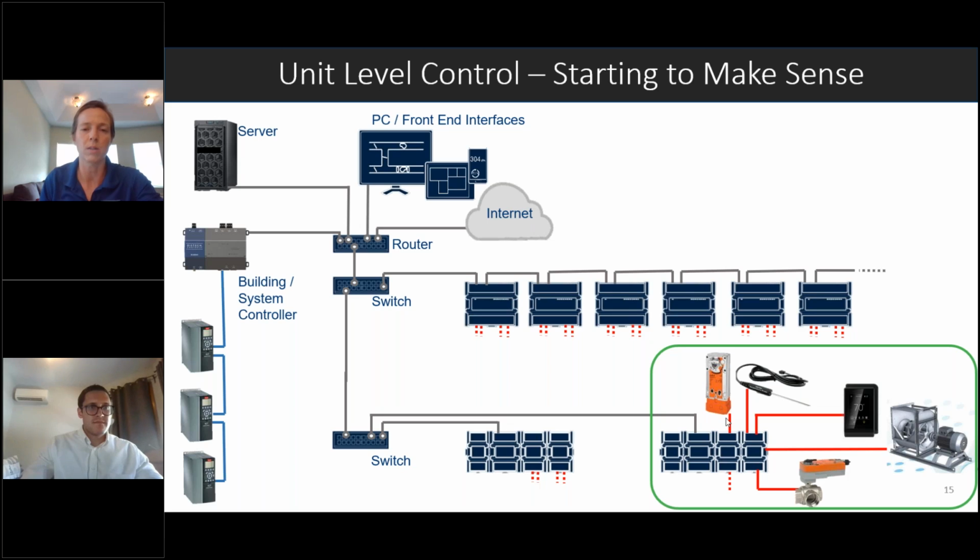But as Grant alluded to earlier, you have to read the documentation carefully, because sometimes there are some field installed sensors and wiring that you need to do. So factory package controls can mean everything from fully packaged, where you just need to bring one cable so it can be tied into the BAS, to things like field mounting and wiring sensors.